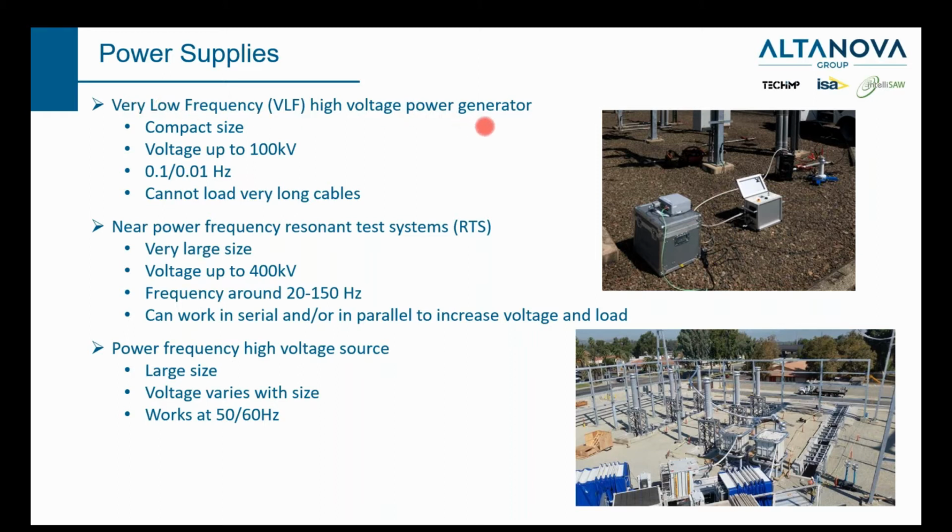And the very low frequency, VLF, is very popular for medium voltage cables. The VLF testing power supply is much smaller compared with the power frequency or near power frequency power supply. Here's an example. This is a 30 kV VLF power unit.